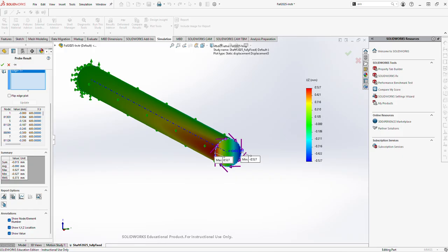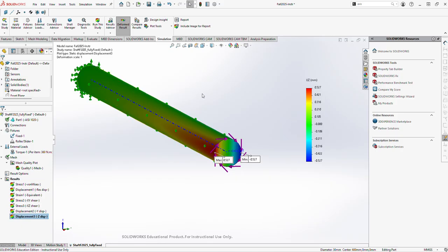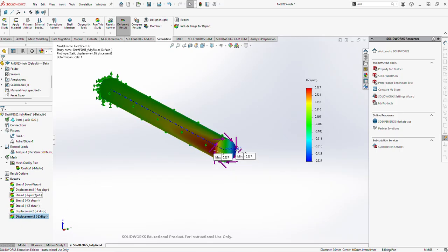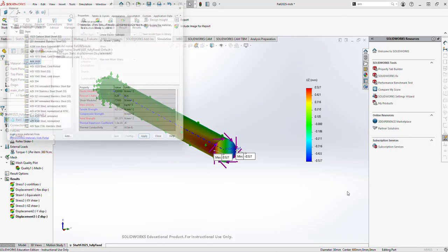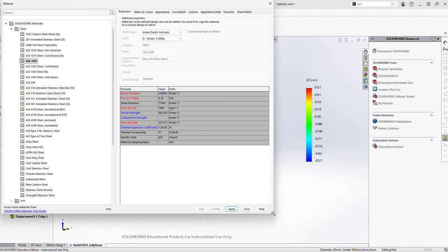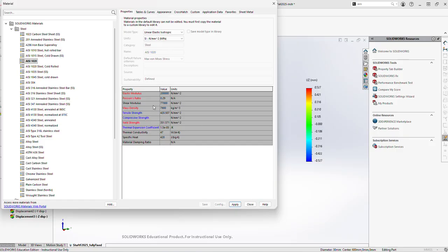And now how you are going to calculate the factor of safety, just like we did for our FEA analysis. For the factor of safety, you'll take basically the shear stress and compare that with the shear strength of the material. Now that is slightly tricky because do you actually have the shear strength or not? Let's quickly look into the material data card. And if you see this, the material data card, you can see here that this gives you the tensile strength, but it does not give you the material's shear strength in this data card.